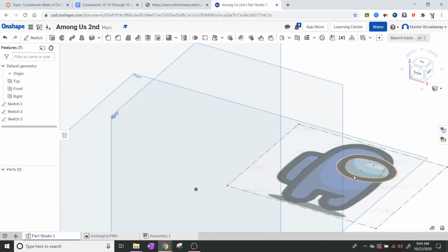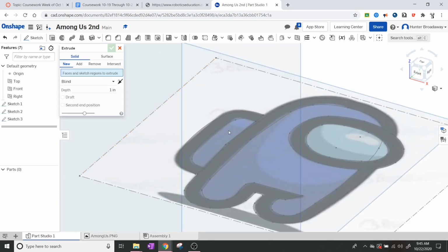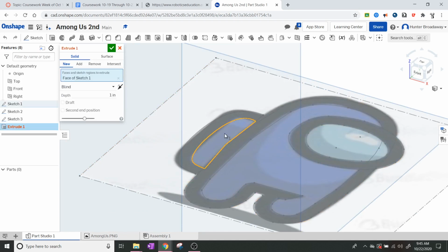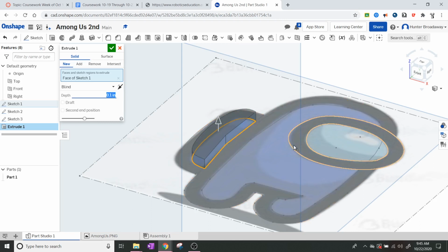I'm going to click on isometric view so I can get a flat version of this guy going. I'm going to click on extrude and then you've got like 80 bagazillion options to click on here. Click on the inner part of the backpack and see if it actually does extrude. Obviously 1 inch is going to be a little bit too large. Why don't we go with 0.1, or a tenth of an inch? And that'll give us a thickness that'll actually work. Okay, does that make sense?